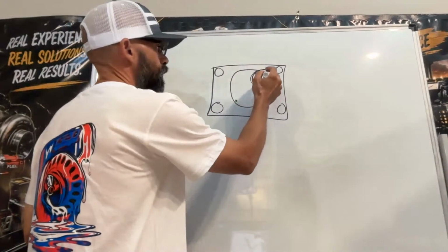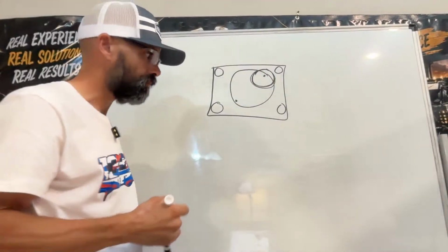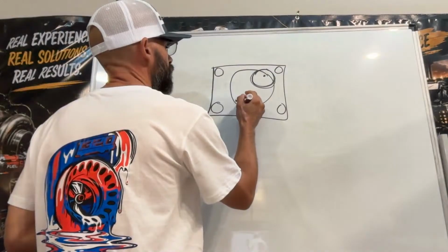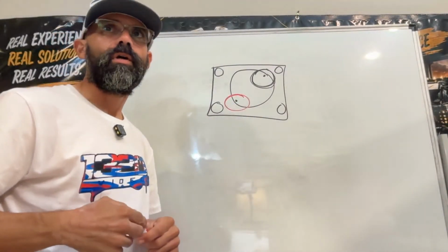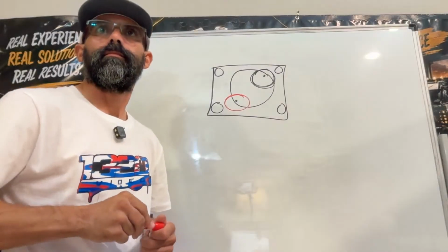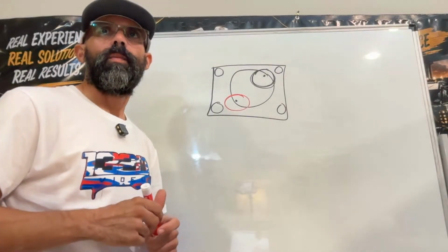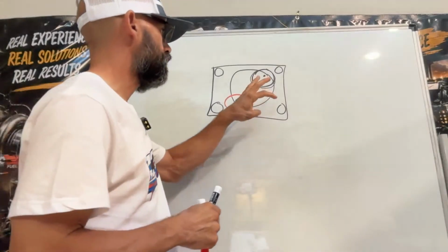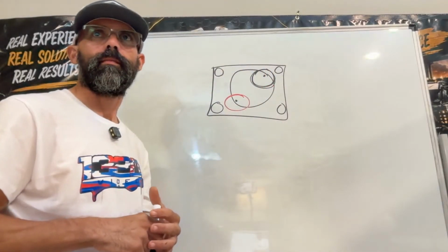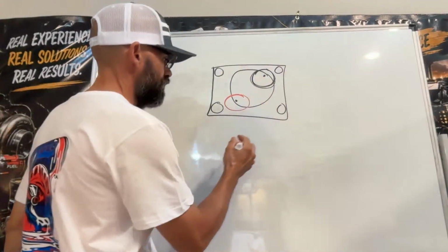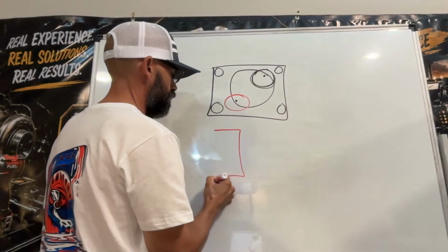So if you put the pin on the wrong spot, you put the pin right here on the wrong spot, you're gonna have issues. You are not gonna have charge pressure, because you might think that, okay, you know what, you just change the configuration. Also, the pump uses a plate between the rotating group.